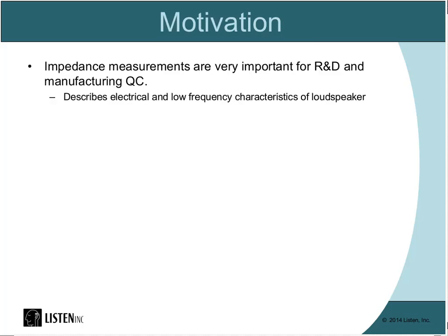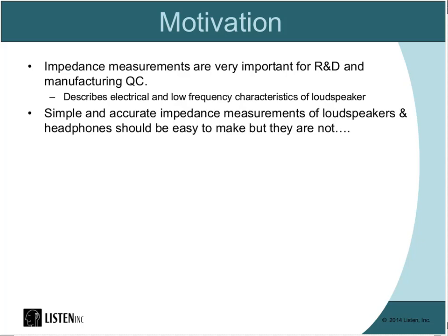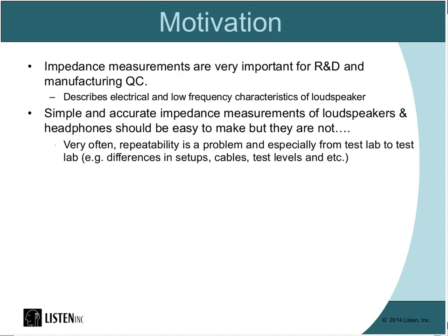Okay, so impedance measurements are very important for R&D and QC. They describe the electrical and low-frequency characteristics of a loudspeaker. Simple and accurate impedance measurements of loudspeakers and headphones should be easy, but very often they are not. Why? Well, for example, repeatability is often a problem, especially from test lab to test lab. It can be due to differences in setups, cables, test levels, etc.